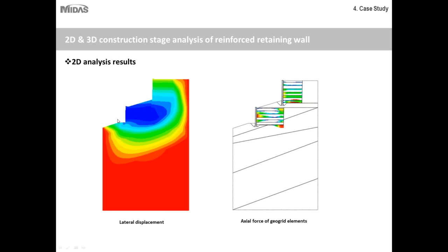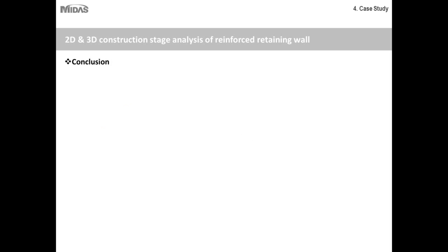Like I said, there was construction going on this side, where these were the retaining walls here. So just to be more clear on the point that the out of plane deformation of the wall is controlled, they checked this model for the 2D analysis and for lateral deflection.